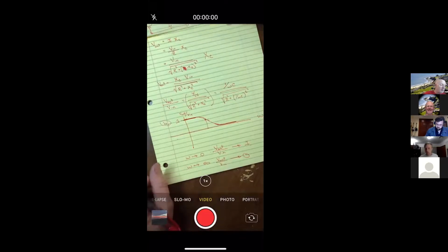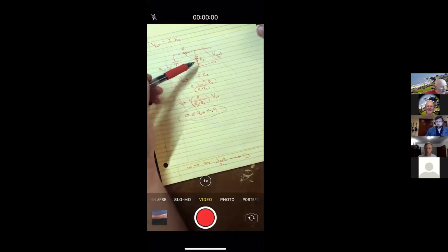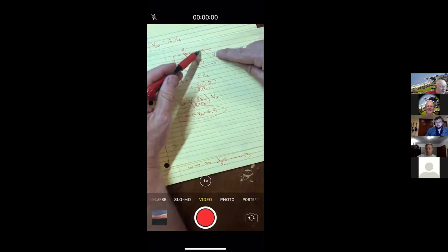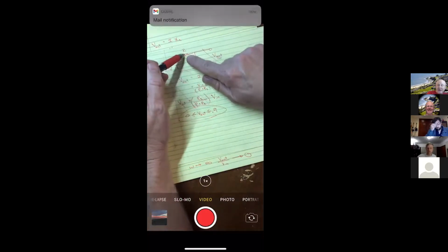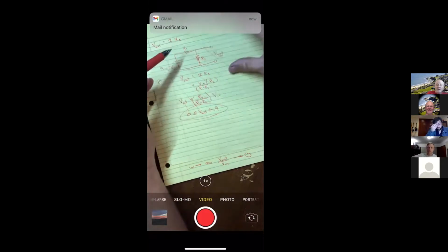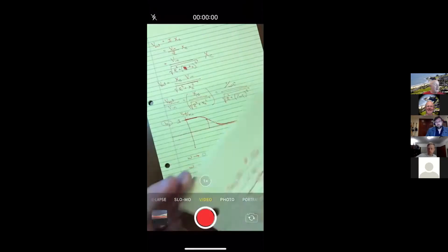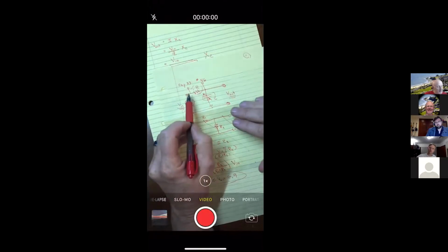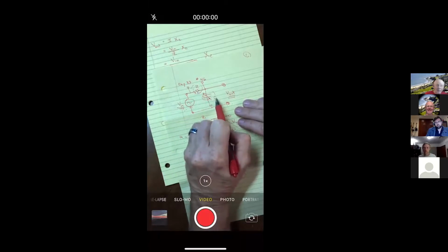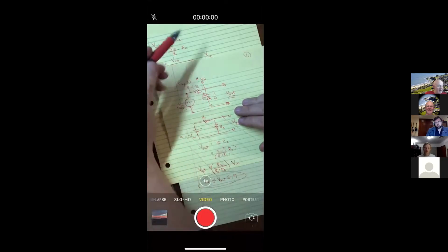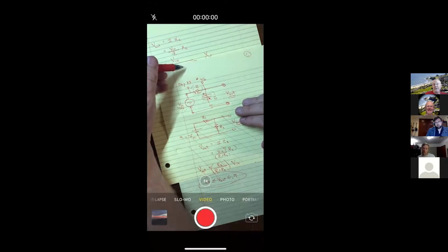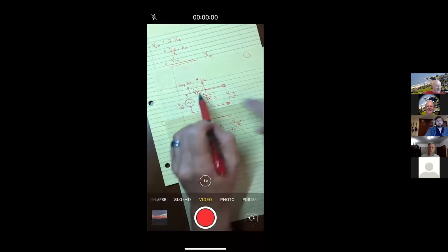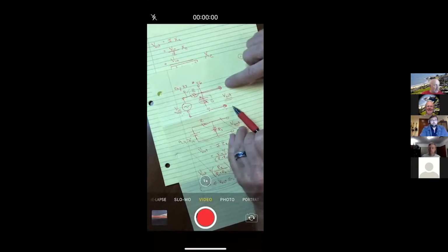Now, as a side note, you could probably see that back here in our voltage divider, if we had, say, R2 really small, so there was very little voltage here, since the two of these have to add up to 9, when this is small, this is big. So these are exactly opposite of each other. As a sound engineer, besides putting one output here, I might put another output on this resistor, because this would be a high pass filter and this would be a low pass filter. If I connected to here, I would be amplifying my high frequencies and diminishing my low frequencies. If I put my connection here, I would get the low frequencies, but not the high frequencies. So connecting here makes a high pass filter, and connecting here makes a low pass filter.